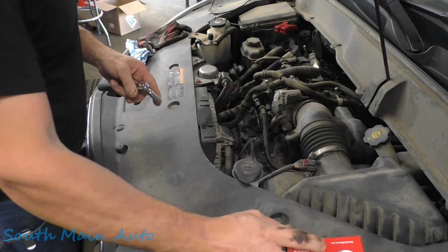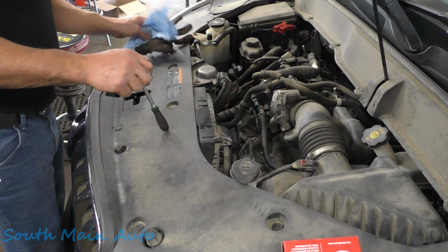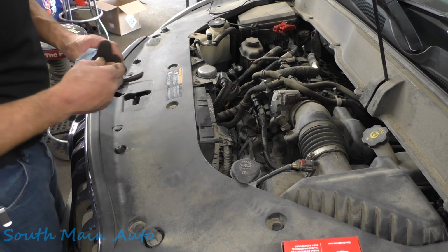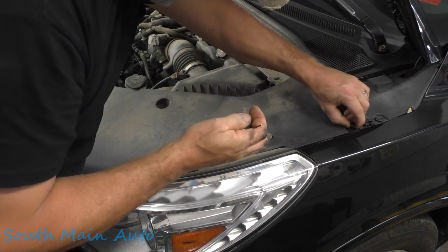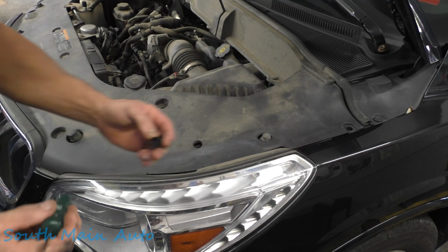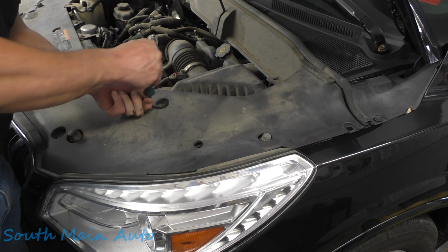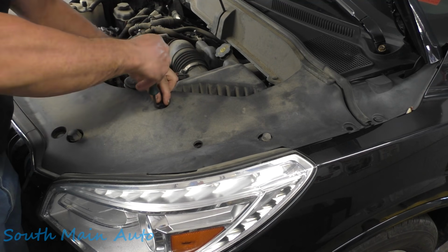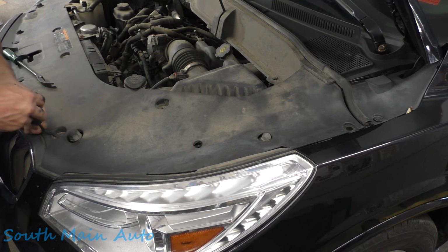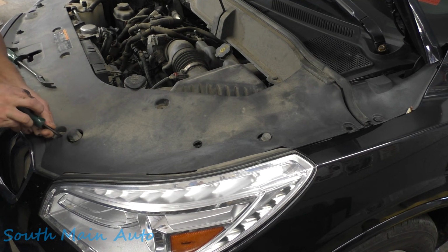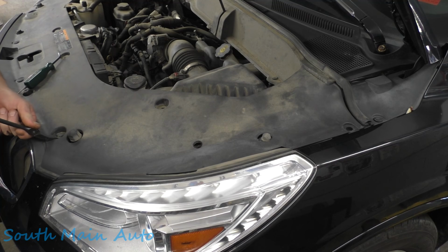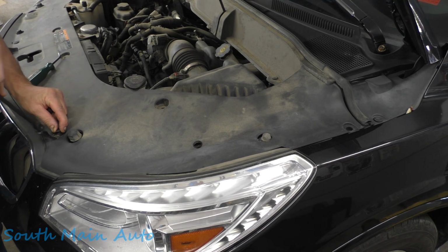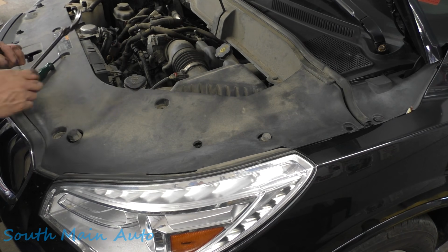Making the mountain. We have to pull this off to get to the radiator cap. We should be smart about it and just go ahead and do that so we can take any pressure off it. So these are pretty easy. You just pull the centers up in them and then the little push nail will come out, and you do that about 10 more times here. Get to those and just keep working your way along. You'll have it off in no time. Sometimes you get one that's stubborn. Get underneath of that little fella. There we go.